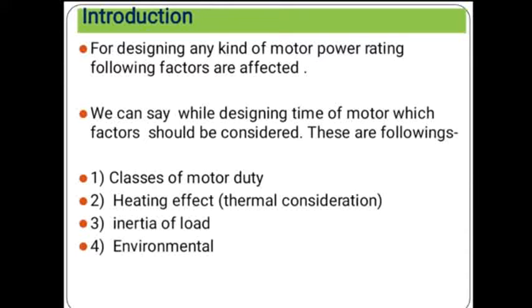So we know that for designing of any type of motor power rating, the following factors are affected, or we can say that while designing a motor, which factors should be considered. So these are the following factors which affect the designing of the motor power rating. First one is classes of motor duty. Second one is heating effect, or we can say thermal consideration. Third one is inertia of load, and fourth one is environmental.